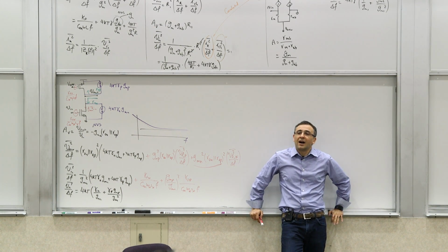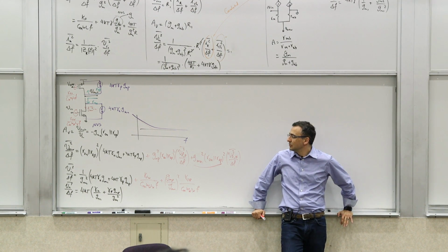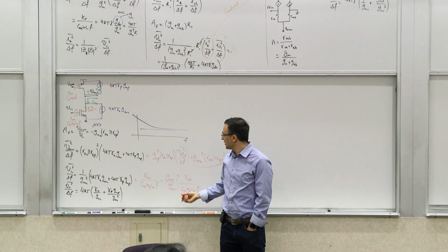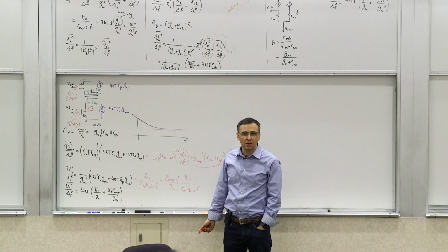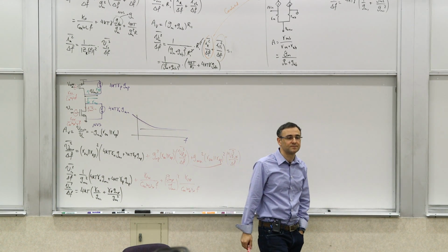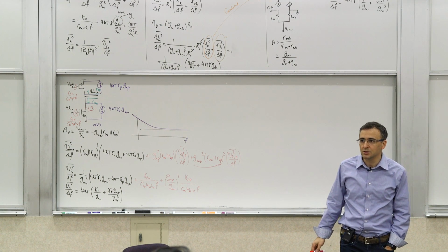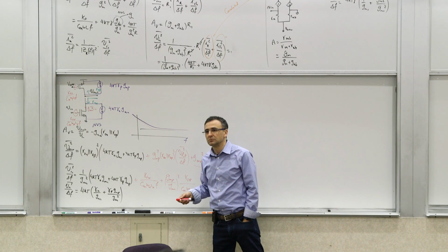So if you're trying to minimize the input referred noise, as far as GM is concerned, the same trade-off applies to both components of the noise, right? Increasing the GM will reduce the input referred noise, GMN. GMP doesn't help, actually it hurts. And we can see that.